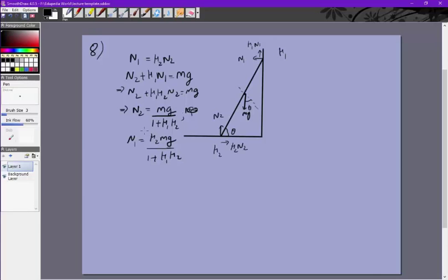Right. So from this we can actually see in the options that they are given such that mu1 is 0, mu2 is not 0, and those are the options given. So we'll have to take care of all equilibriums then, not just translational equilibrium, but the rotational equilibrium has to be 0 as well. So we can write two equations for rotational equilibrium, one about this point and one about this point. About the lower point, the equation will be, if this is L, this is L sine theta and this is L cos theta.